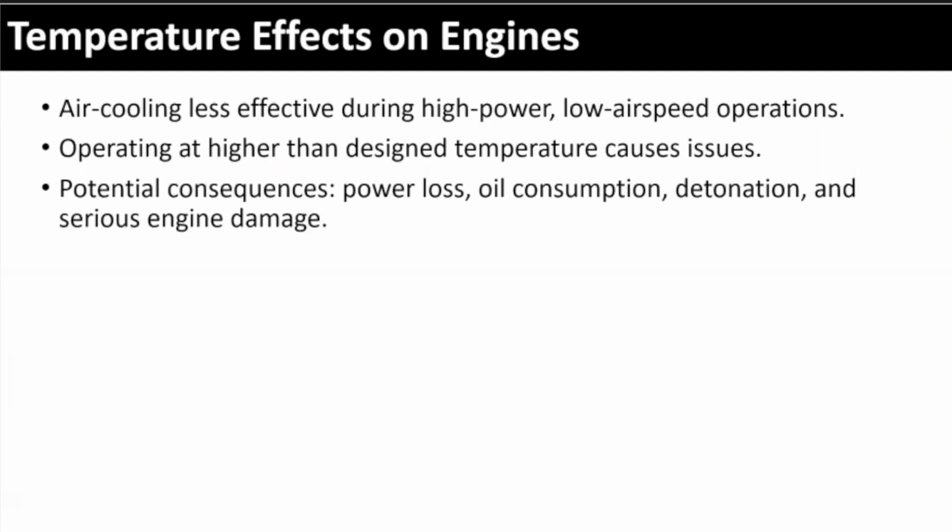All right, we talked about this earlier too. High speed, high power settings, low airspeed. What are we running the risk of? Overheating, right? Because we don't have that flow. We're operating at high power settings with not enough airflow because we're at low speeds. We want to make sure we try to avoid those situations.